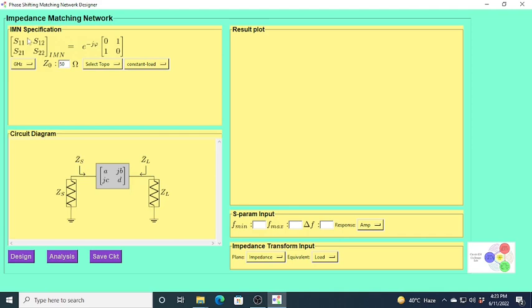In a typical matching network, S11 should ideally be 0 and S22 also should be 0, and S12 and S21 should be 1 in magnitude, and the phase shift is denoted by phi. Phi is the amount of phase shift. When the signal travels from port 1 to port 2, the signal will get a delay of phi. I will give you the details of what this phase shift physically means. It is basically the phase shift of the Thevenin voltage source, which has been introduced in the paper.